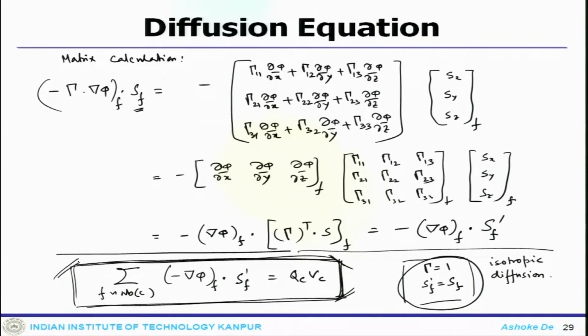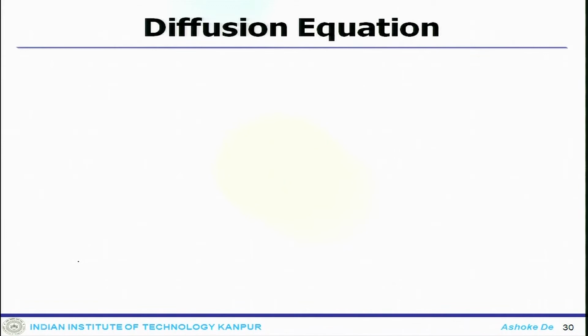Now, the part I would like to discuss is that we have got this discretized equation. For the solution, there are some iterative processes involved, and there you need to do some sort of relaxation, whether under or over, depending on the situation.